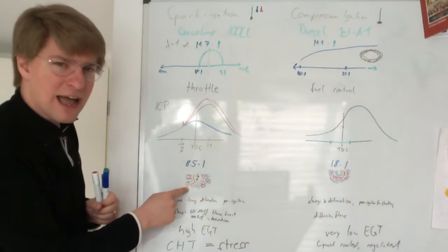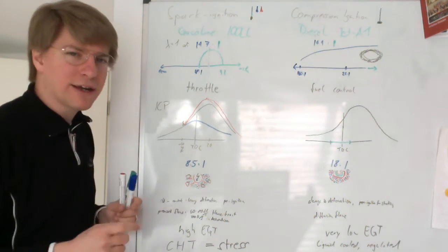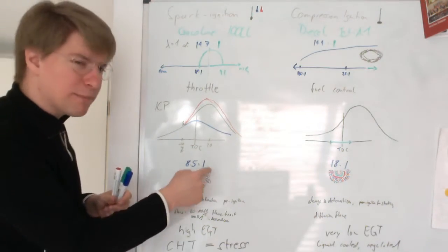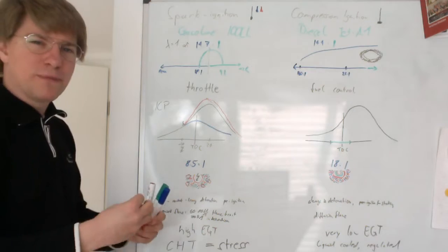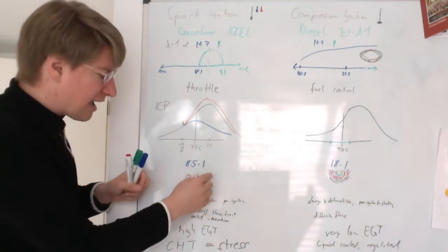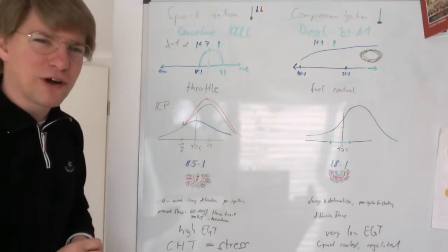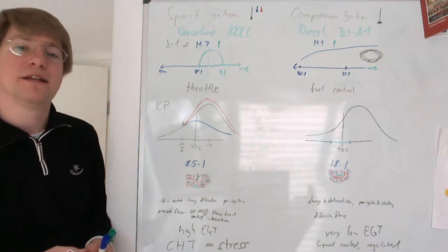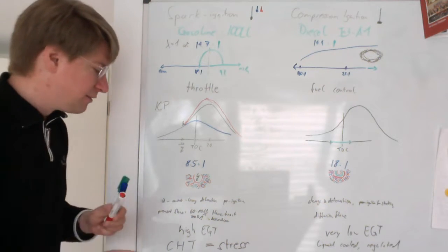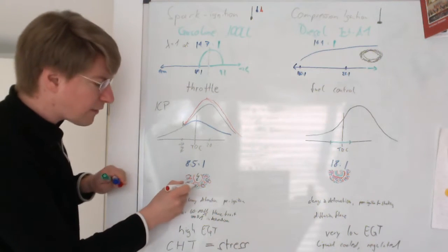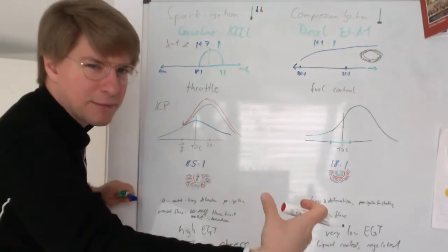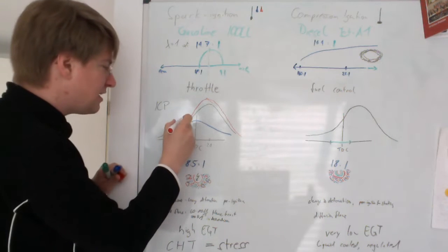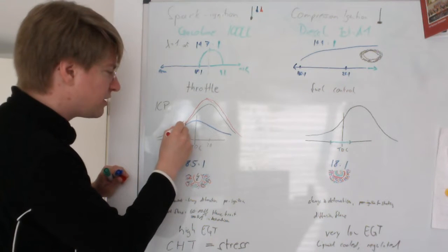So what we now have is those little pockets of combustible mixture spontaneously igniting, and we have several flame fronts going at the same time. And this is what we call detonation. So if this happens, we get those little pockets igniting all on their own before the primary flame front has reached them. And this is when the ICP, the internal cylinder pressure, begins to look something like this.